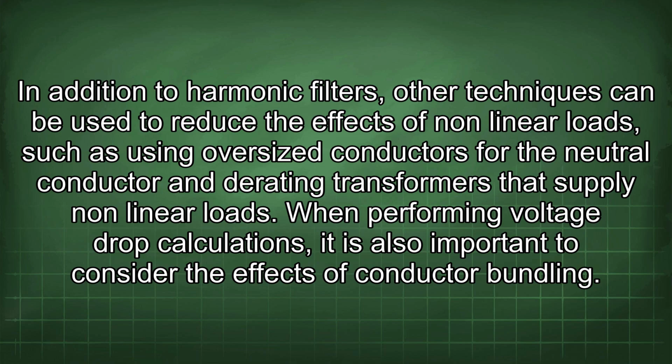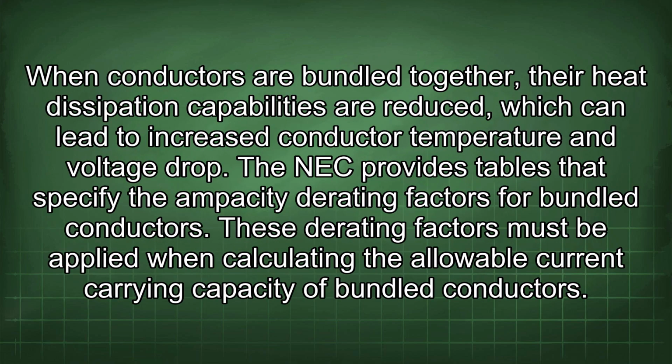When performing voltage drop calculations, it is also important to consider the effects of conductor bundling. When conductors are bundled together, the heat dissipation capabilities are reduced, which can lead to increased conductor temperature and voltage drop.